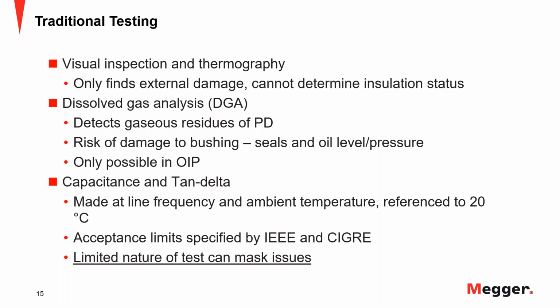The other thing that you can do, of course, is a thermal scanning. And that is very interesting to do, in the sense that with the thermal scanning, you can see any type of issues with connections, right? External connections, especially if you have a power line being connected from your switch yard to the bushing. And if there's any loose connection there, that will create a hotspot, and that hotspot can derive into additional issues with the operation of the system. So visual inspection and thermal scanning are some of the easiest things to do.